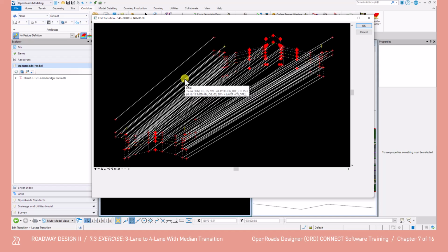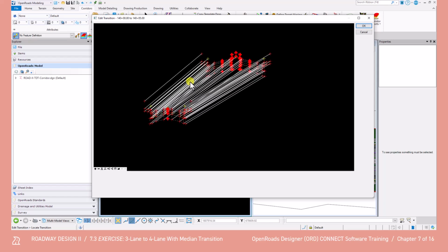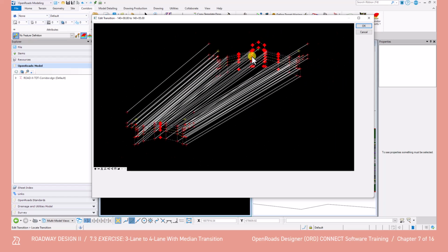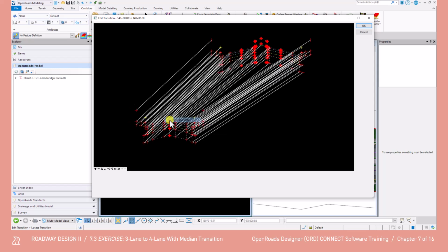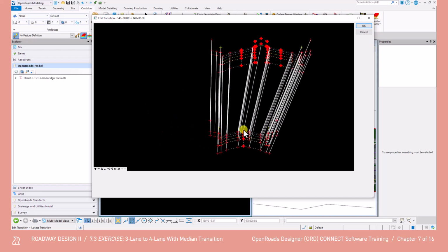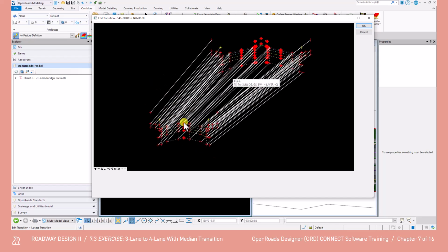Within this window, you can zoom in and out with the mouse wheel and see what points in the template have automatically been linked to one another. This will happen if the points in both templates have the same name. The bold crosses represent points that have not been linked. Right-click on one of the template ends and notice a Move Template prompt appears. This allows the selected template to move around within the window to see a better view of what is linking.